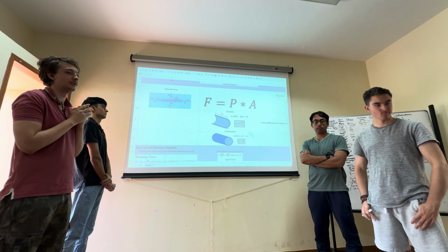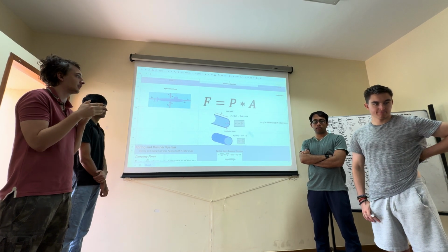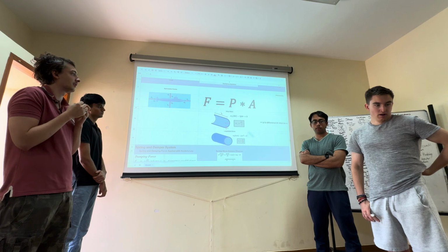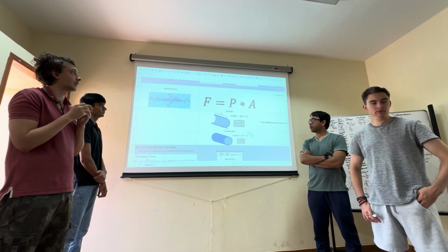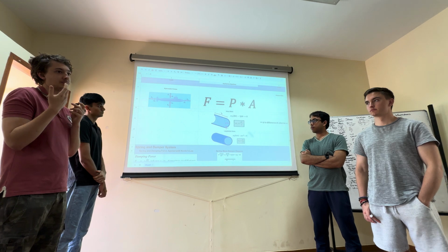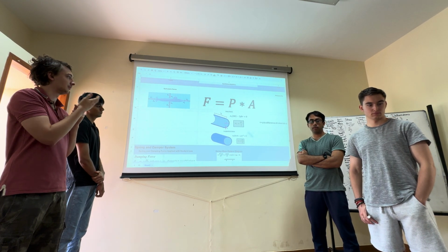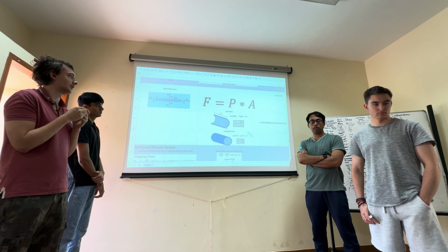We can relate the difference in pressures on the outside and inside times the radius of the structure divided by the thickness of the structure to get the stress, which is also the pressure in a way, in this scenario. And the same goes for longitudinal stress; it is a similar equation.